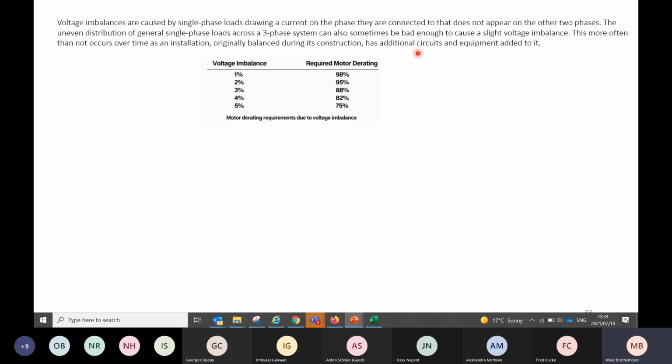So here we look here. Let's imagine this is a motor supplying a chiller with constant chilled water in a building. If I have more than 1% imbalance, I'm going to derate the motor by 98% of its workload. So if it's spinning an impeller and I need to supply 10 liters a second through my chiller, I'm now going to start supplying 8 liters with the risk of my evaporator starting to freeze. Okay? Or my flow rate, I'm going to have a lot of alarms on site because of the flow switch that's fluttering.